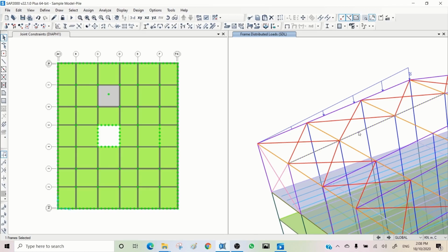Depends on the importance of the structure. It's back to the design criteria dictated by the client to you. If you want to go for worst case scenario, you can, but it may not be cost effective. So you need to see the ambient temperature at the time of construction, and then see when the structure is constructed and restrained, what would be the difference in the hottest and coldest compared to the time of construction.